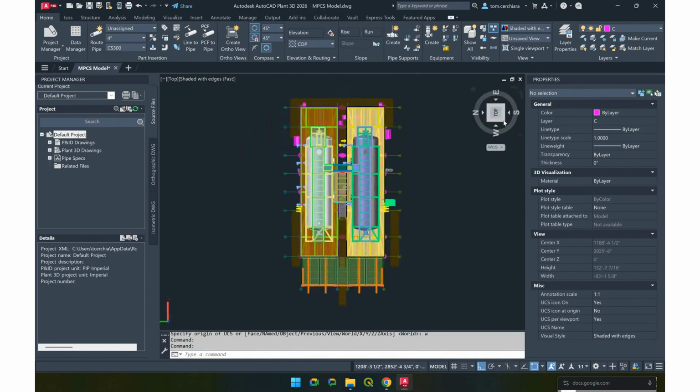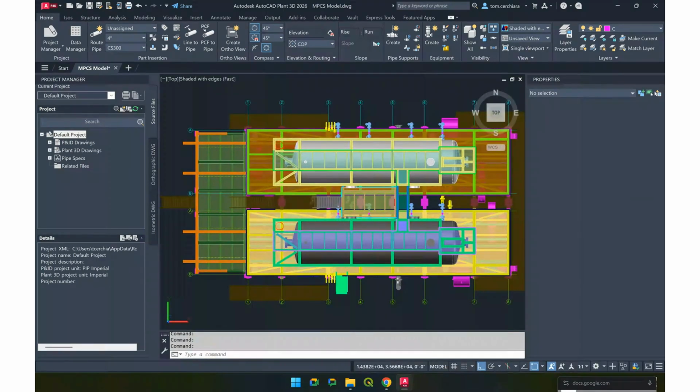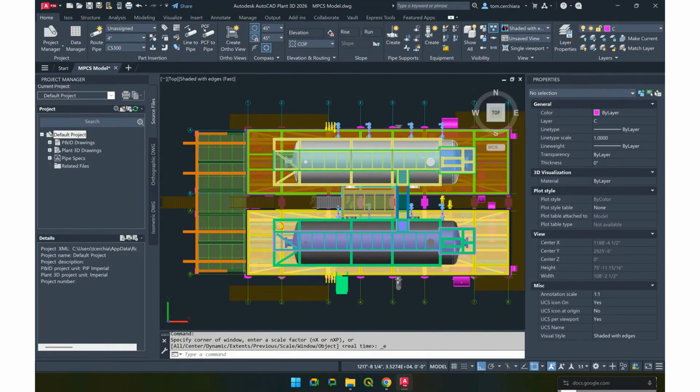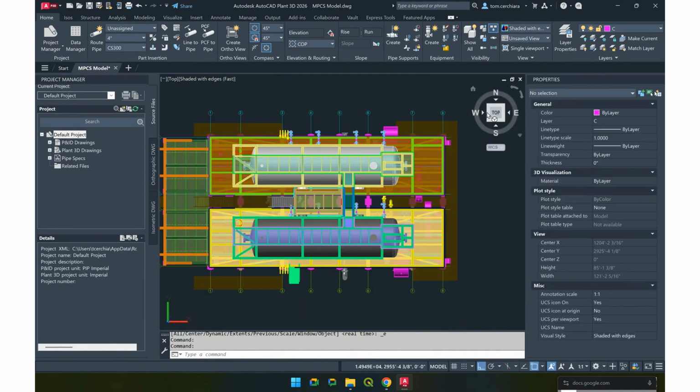And we'll give this a little bit of a spin. So north is up. Okay, so there we go. Now we're looking at the top and north is up. I encourage you to check this fairly often. I've had a couple times where it seems to have reset on me, either when I undid something or just unexpectedly ended up being twisted again. So make sure you are looking at top and north is facing up. Otherwise, you will have problems. It will snap to wrong coordinates and things will not line up.